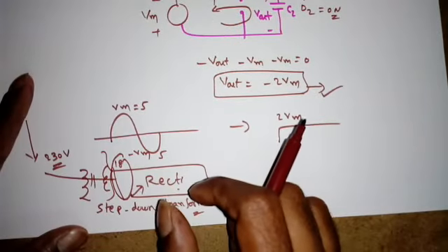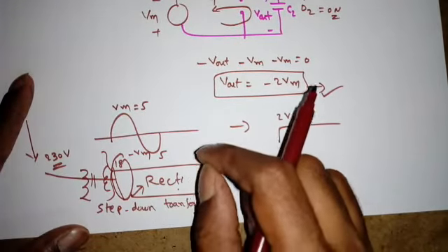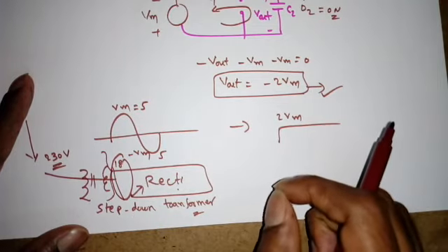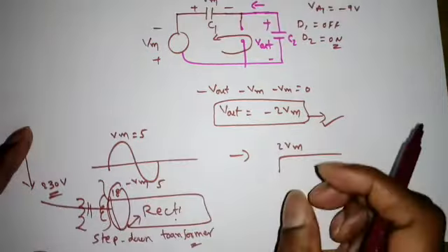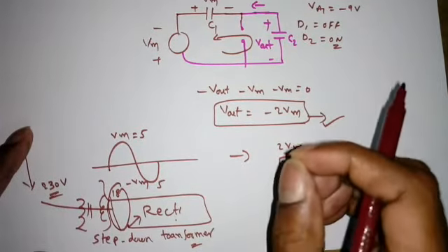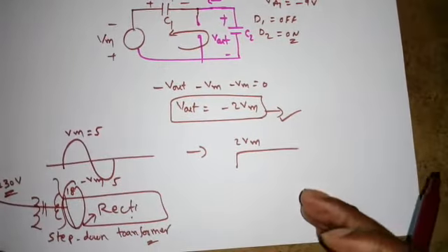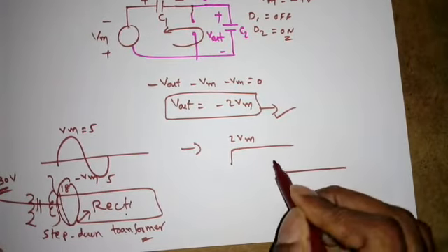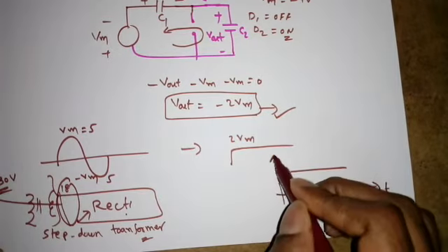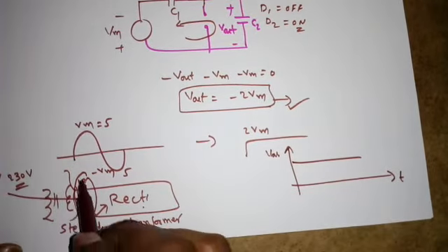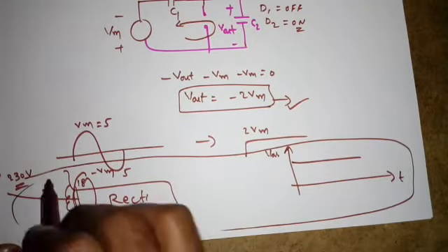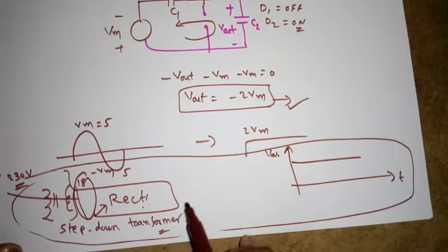Whereas if we first use a rectifier, it will convert from AC to pulsating DC. Then if I add the capacitor filter, we'll get approximate DC, but there will be some ripples. Then if we add a voltage regulator, we'll get perfect DC voltage, right? So that's why when I want to convert AC to DC, we have to use this circuit only: rectifier, then filter, then voltage regulator, etc.